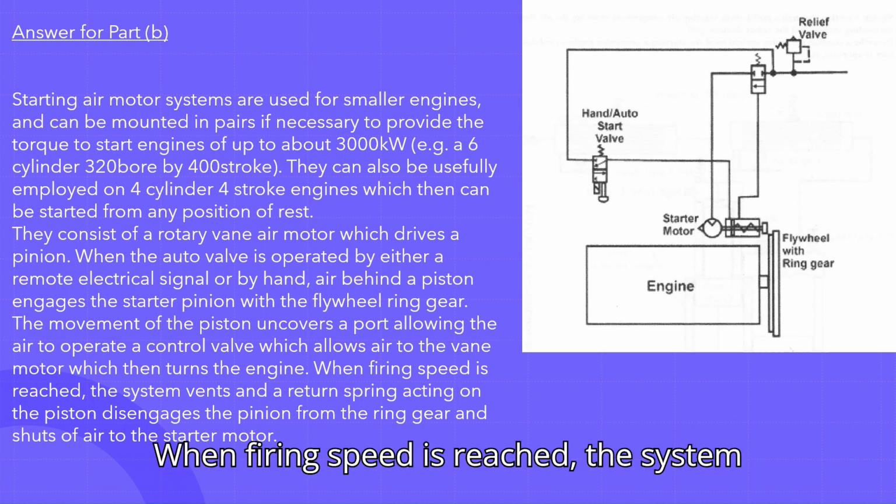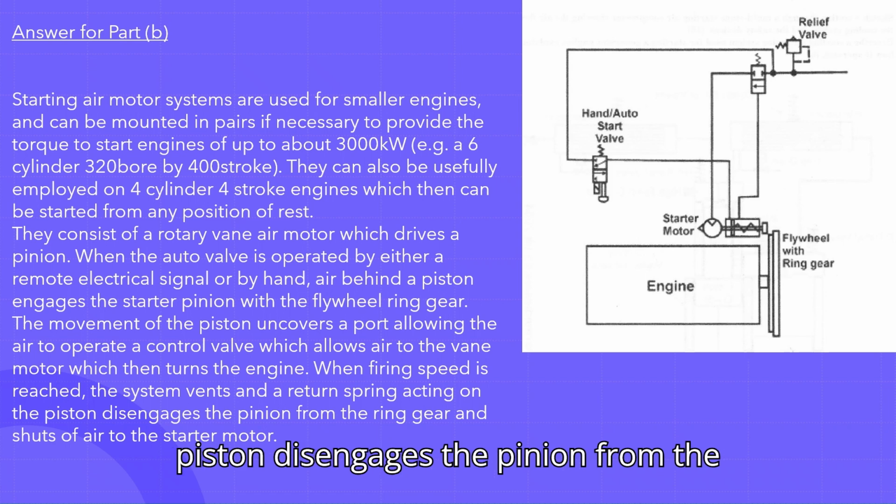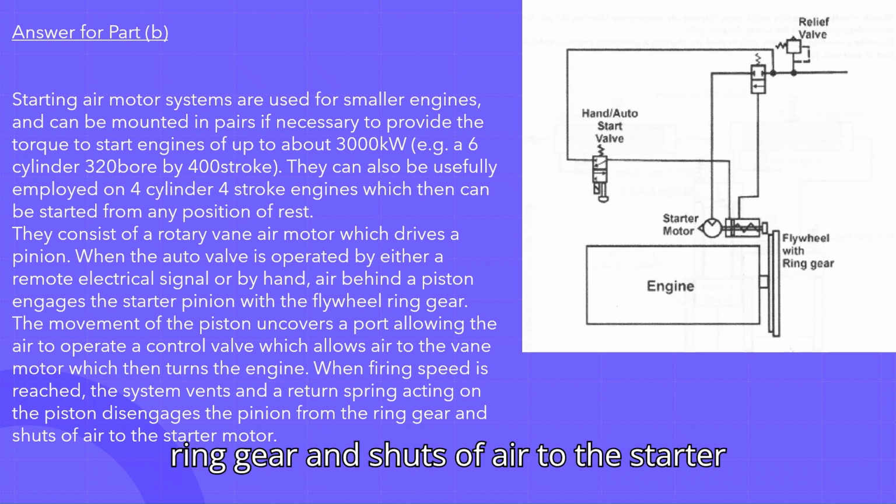When firing speed is reached, the system vents and a return spring acting on the piston disengages the pinion from the ring gear and shuts off air to the starter motor.